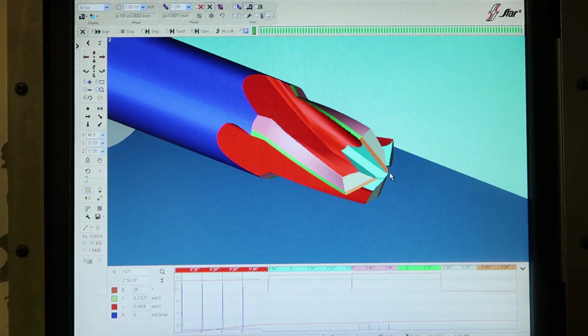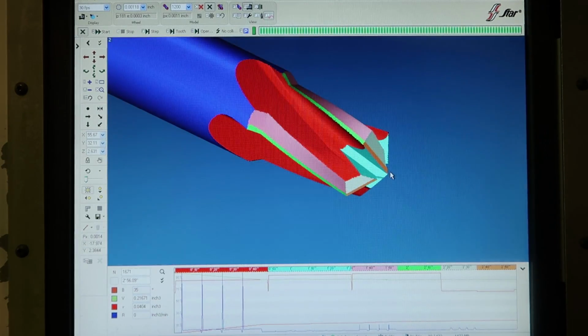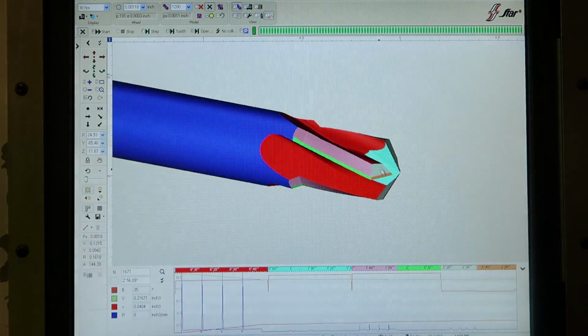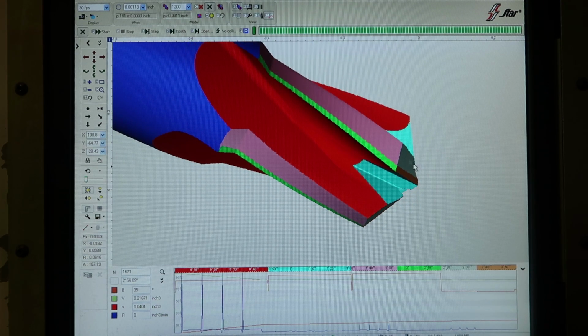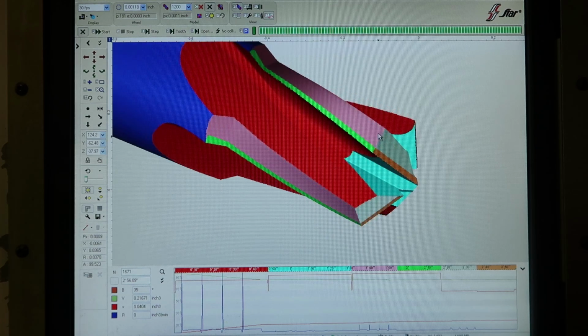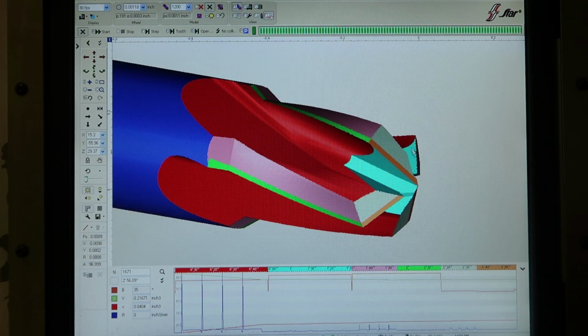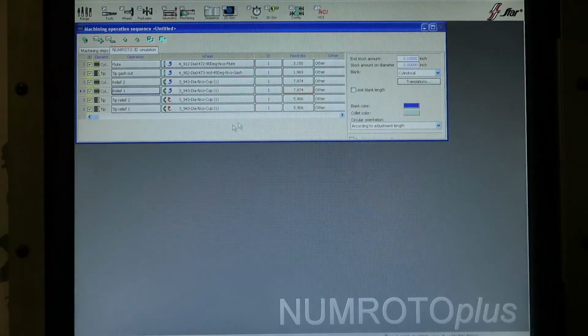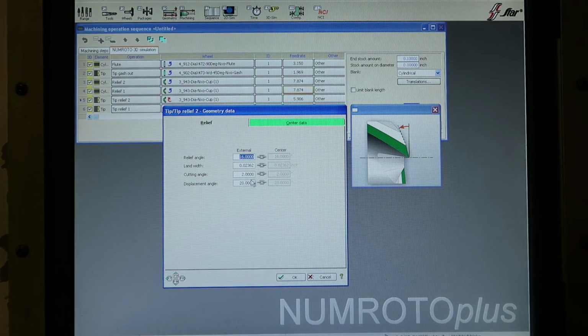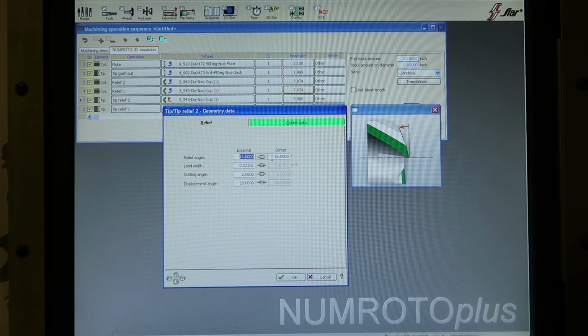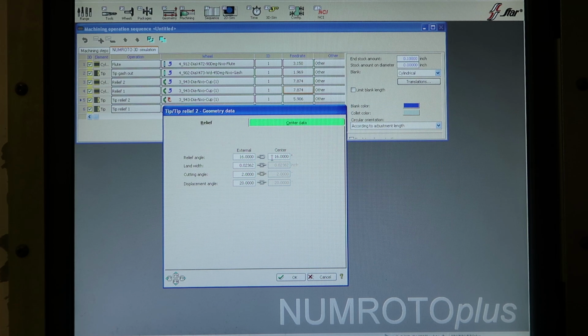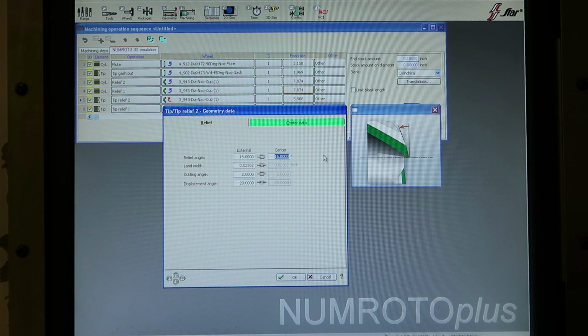Now these clearance angles, because we've changed the angle of the tip of this to grind an angular, it might rub here when it's going around this, when it's making this chamfer, because the secondary clearance angle really isn't steep enough, and we might have a problem here. So I think we're going to increase that on the tip here. And we're going to change it as we come. We're going to start, 16 might be all right there, but as we get up to the center of the tool, I want to go more like about 24 degrees, I think.